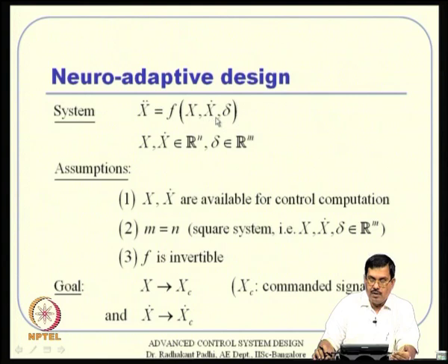So, for example, that phi theta psi if you remember, then phi dot theta dot psi dot are functions of P Q R, but they are not functions of control actually. But if you take double derivatives, then P dot Q dot R dot appears, and then the deltas will start appearing. So, in other words, the flight control problem that we are typically interested in is of relative degree 2 actually. So, that is what we are considering here.